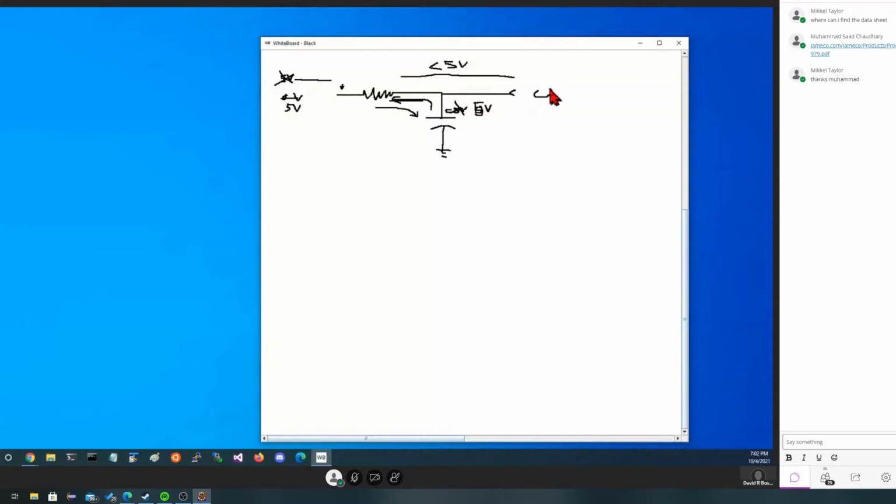But that means the whole time, I'm going to put a big eyeball here, whoever was looking right here didn't immediately see 5 volts. And they didn't immediately see ground. Instead, there was some sort of a delay introduced. And the delay must have been some sort of a function of the changing voltage here. So what we need to know is, how do we determine what the time constant is? Basically, how long does it take this to charge or discharge given a particular value for its capacitance?